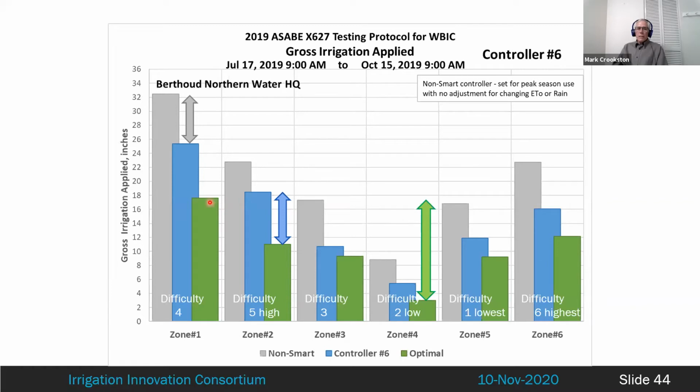So if you look at the highest plant requirement compared to the lowest plant requirement, that's the potential that could be saved from simply changing plant materials and properly irrigating. It's kind of dangerous to say that all plantings and all landscapes in northern Colorado or anywhere should be of this kind. But it does say that there are multiple fronts where we can achieve additional water conservation and do a better job of managing irrigation.